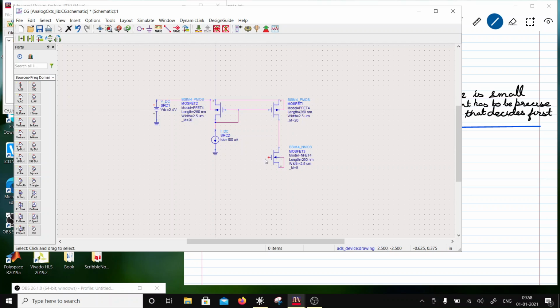Okay, so now in this case, roughly the voltage which we found at the gate, DC voltage, was 0.612 from the previous session. That's V overdrive plus VT roughly, right? So I'm going to place two sources here. One will be called VG and the other one will be called VI.